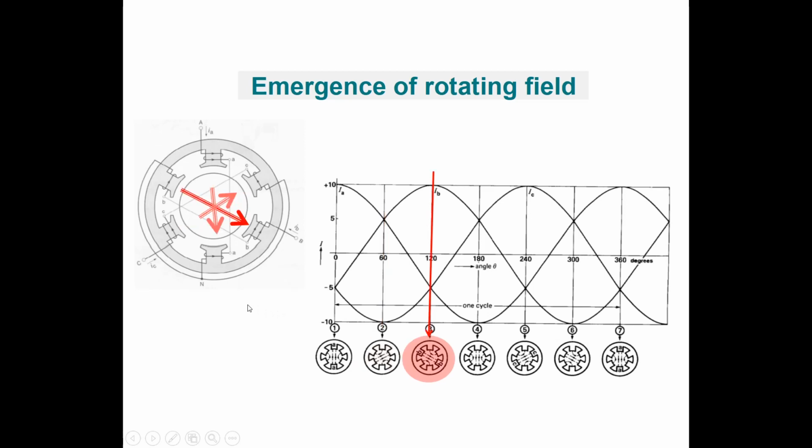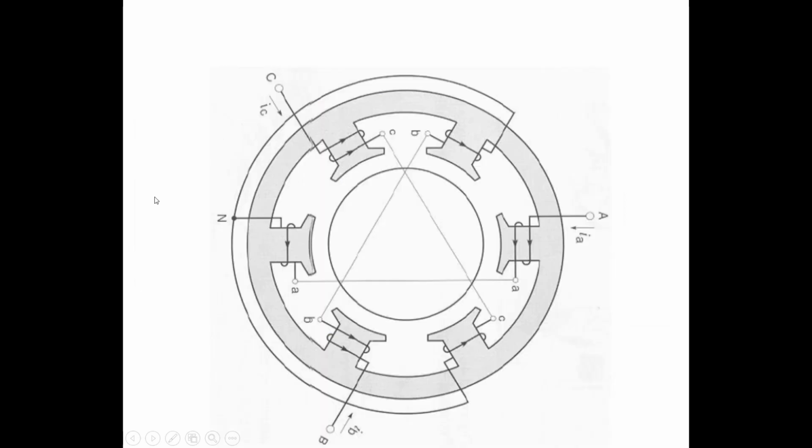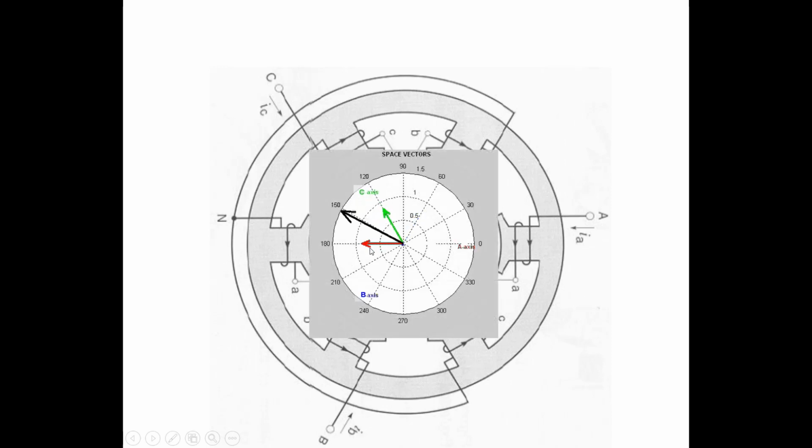And of course that happens all the time, at every change when we shift the angle around the stator. What happens is that at every point at the circumference of the stator, the flux has its maximum value, 1.5 times the flux of one coil, and has a constant value. So at every point my flux, so my torque, has a constant value, and that can be shown over here when we have this animation.